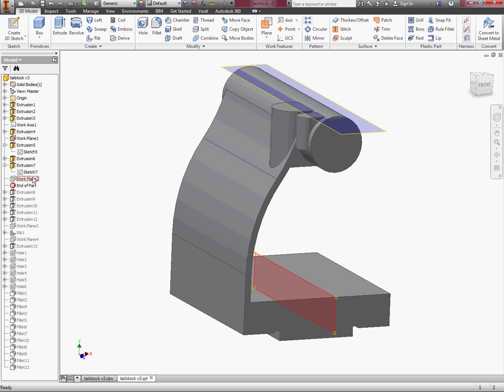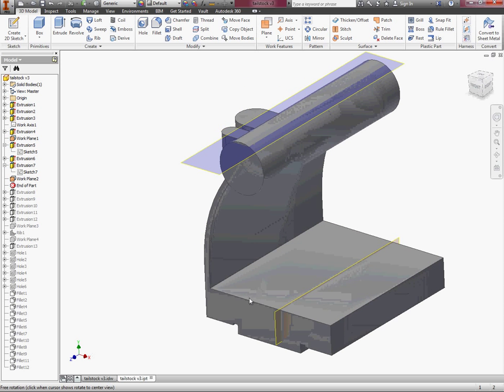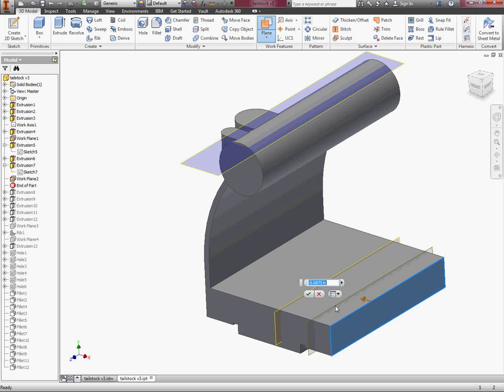After that, we throw another work plane in right here on the base, and that work plane was simply an offset from here. Remember how to offset? You just do plane tool, left click, hold, drag in, and if it says it's negative the direction you want, just keep it negative and go in a certain distance. This work plane is going to be for the faces of the little side walls. There's a dimension that shows us what that needs to be then.